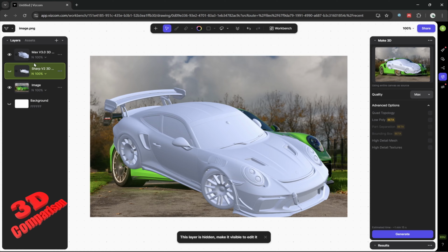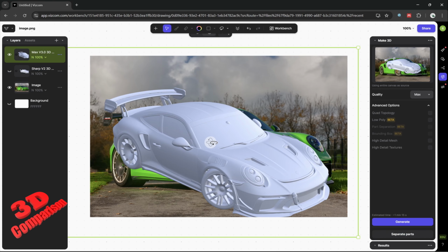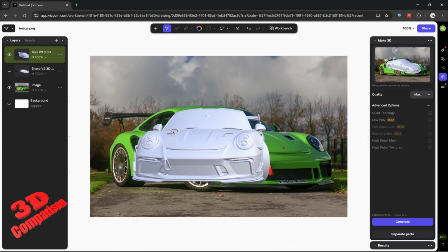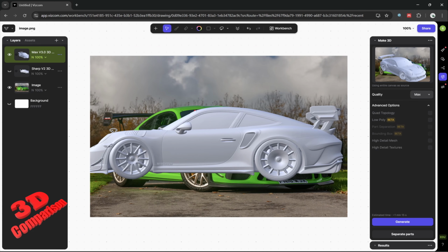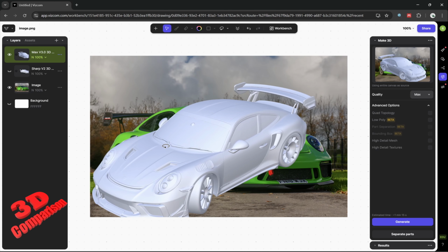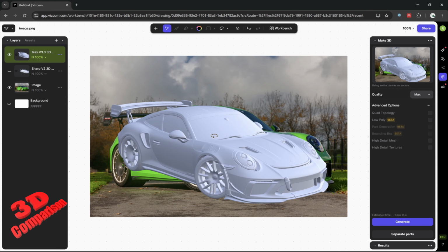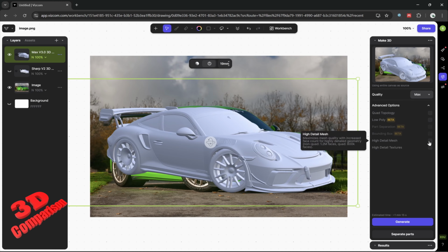And as we can see, the total amount of details is a lot improved. And we see over here how smooth those lines are. We can also choose the high detail mesh, and this will be kept for non-quads, like the one over here, made from triangles, up to 1.2 million faces. We can also define this as quads, so all the way up to 800,000 faces.